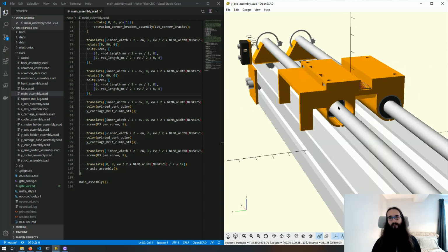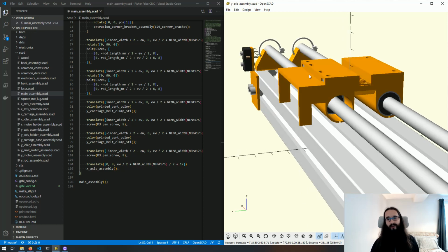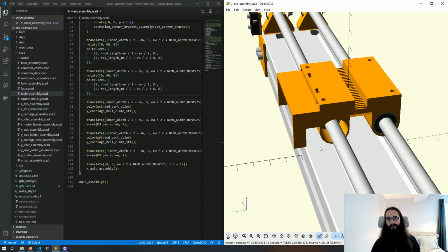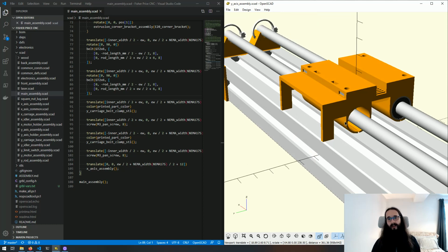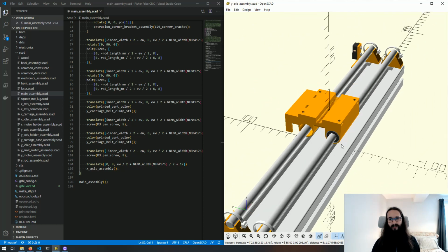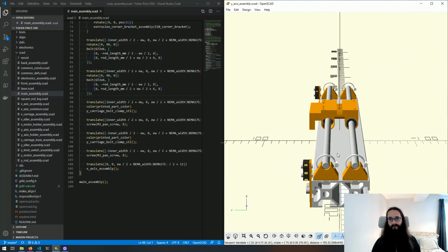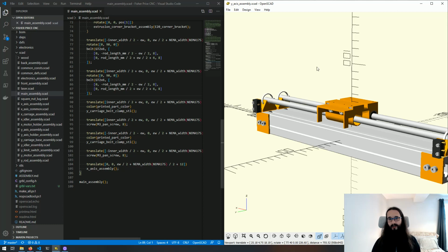Certainly, it has a facility that if you're running slightly more advanced stepper motor drivers, like the Trinamic ones, you could possibly omit this and just rely on the feedback from the motors themselves and what the drivers give you. But I'm not doing that, so I've opted to just use normal limit switches there.